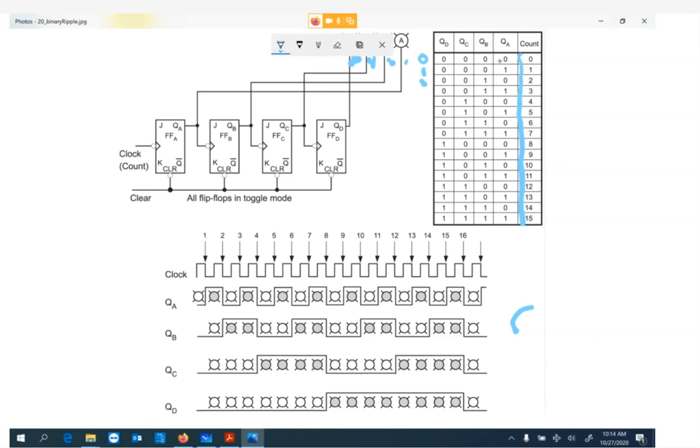But our first pulse here, when the clock goes low, A pulses up, right? So once again, our J is going to be 1. When our J goes 1 and our clock goes up, it outputs QA. At the same time QA goes 1 here, it's feeding a 1 into our inverter gate. Then on the next pulse, A goes low, but B goes high. So we've counted to 2. So that means this will output a 1, and so on.